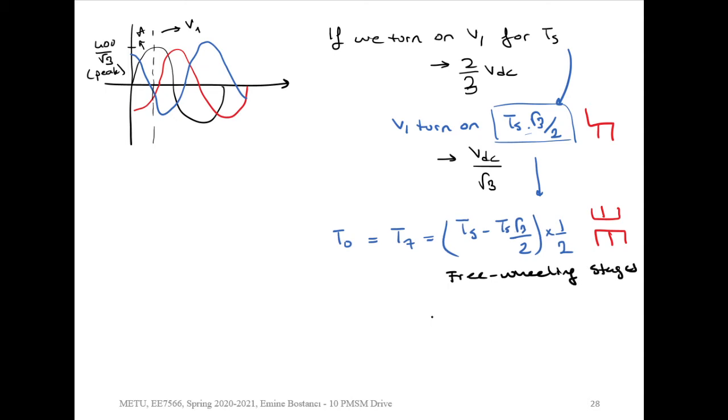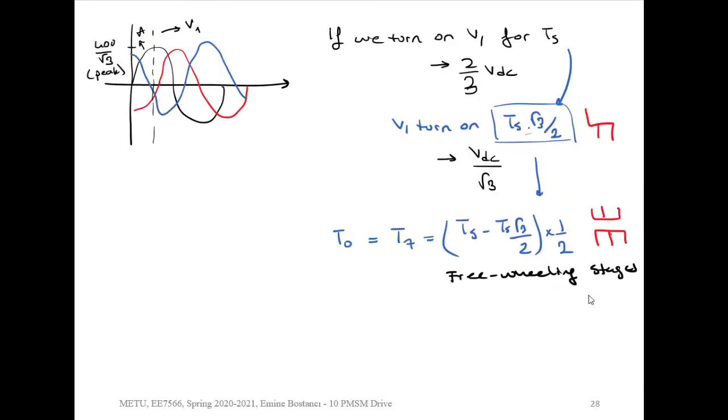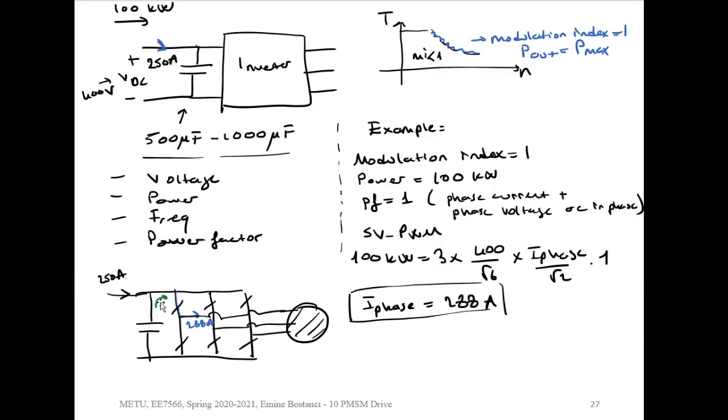In this case, during the turn-on active stage, we are going to ask for more current, and the current higher than what the DC link supplies is going to be supplied by the DC link capacitor. And during the off times, the DC link voltage is going to be filled by the battery.